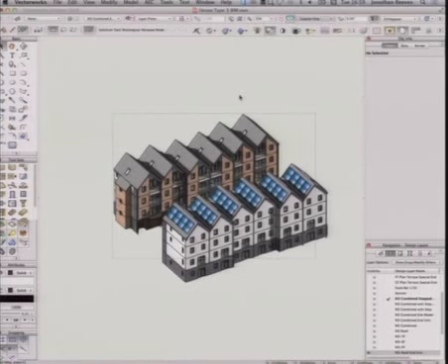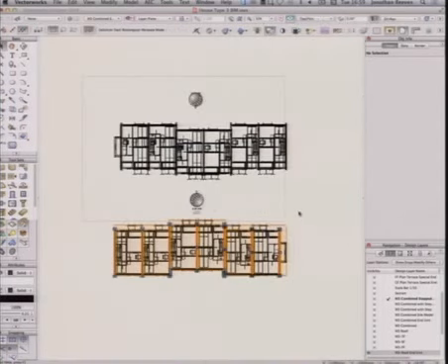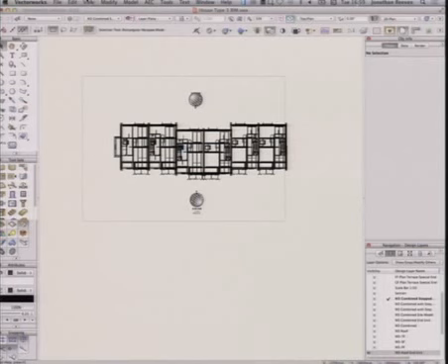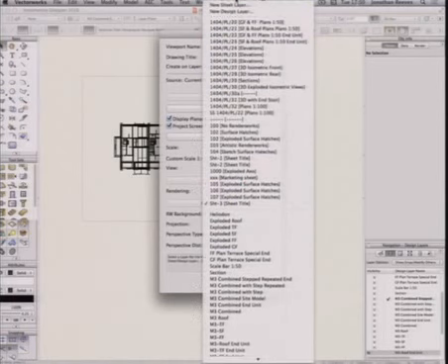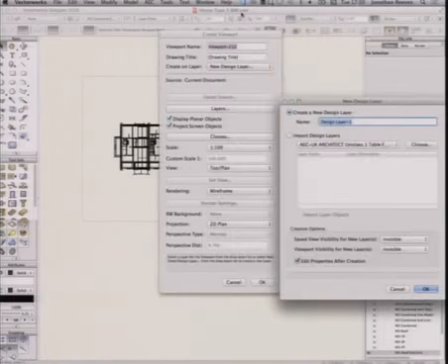Okay. Hopefully that's something for you to have a look at. If you've not used design layer viewports before, they're very similar. You just go create viewport, and instead of selecting the good old sheet layer, go up to design layer and do it. It's really, really easy to do.